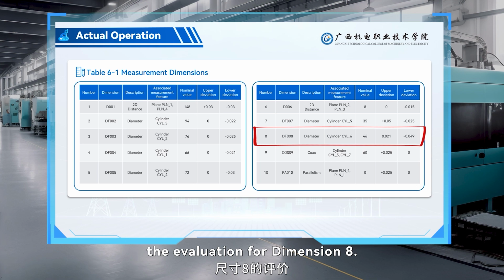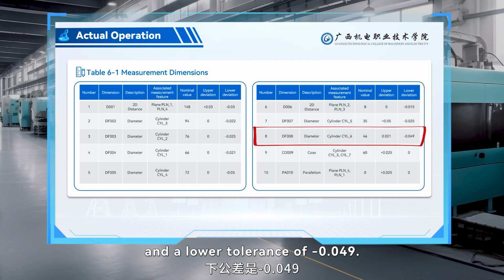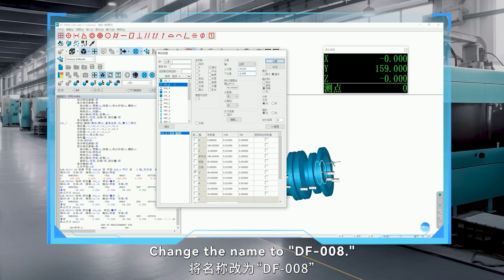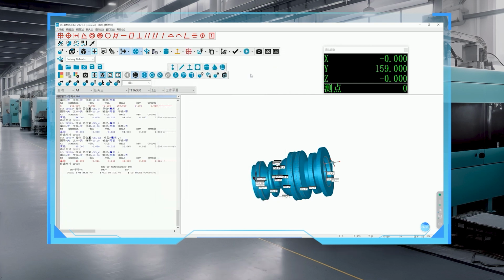Similarly, we need to complete the evaluation for dimension 8. Select cylinder 6 and the diameter. The tolerance values are 46, with an upper tolerance of plus 0.021 and a lower tolerance of minus 0.049. Change the name to DF008. Click Create to complete the evaluation for dimension 8.